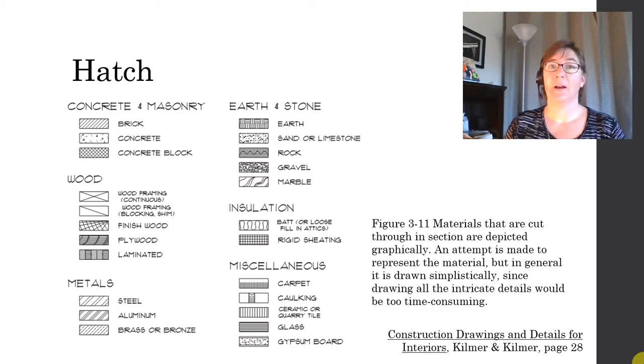Hatch patterns are typically used in architectural drawings and technical drawings to show the different material types. They're a graphic indication of what something is, especially if we've cut it through in a section. So on the screen here are some typical or standard material types and what they might look like